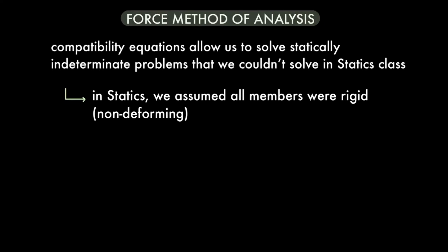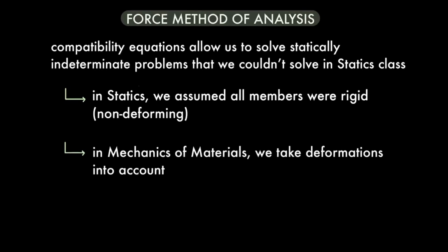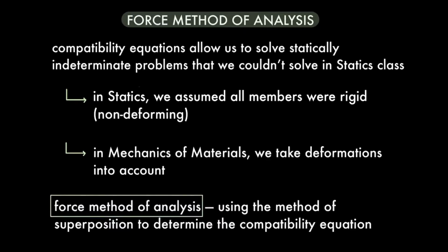If you think back to statics class, you may remember that we used to assume that all members were rigid, so we didn't take deformations into account. But now that we've learned the displacement formula, we can use it in mechanics of materials. More specifically, we'll use the force method of analysis for axially loaded members, which basically involves using superposition of the forces acting on the free body diagram.